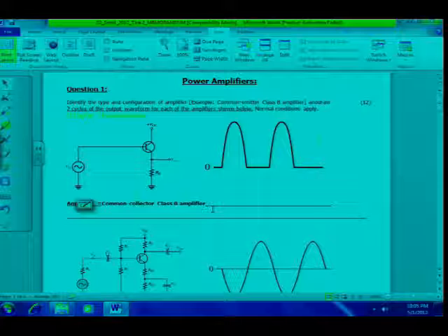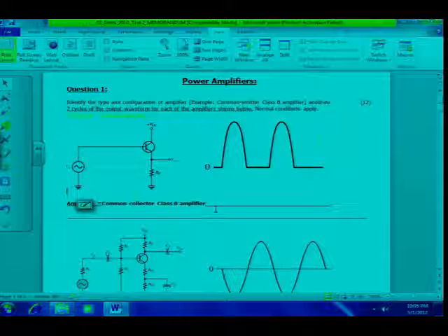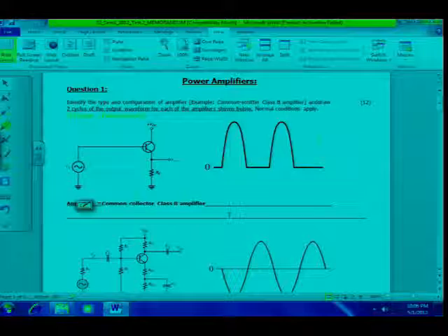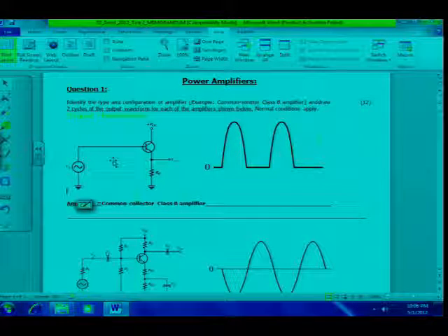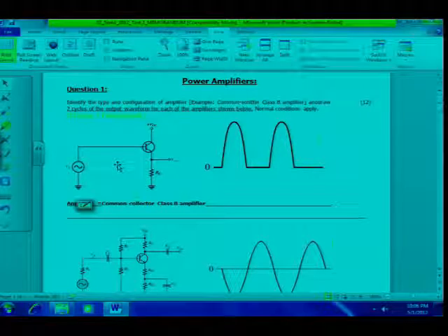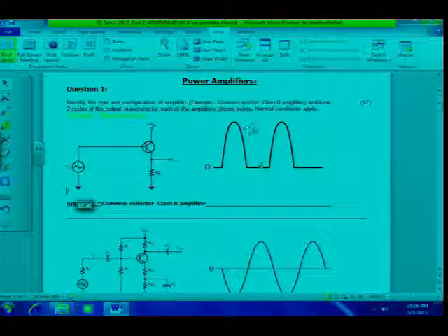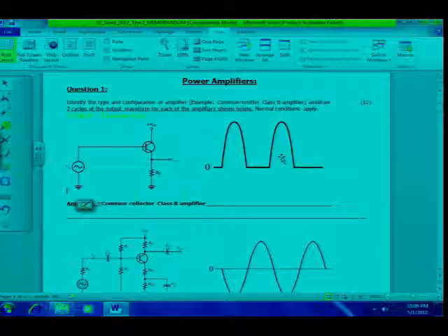The first amplifier that we can see there is a common collector. If you can still recall, how do I recognize? I go and look where's the input signal applied, where's the output signal taken from. So the remaining terminal is the common terminal for both AC and DC signals. In this case, it's the collector, so it's a common collector. You get 1 mark for that, and of course it's a class B amplifier because no biasing has been applied to this amplifier. So for the sinusoidal signal that's shown, that is what I will see on the output waveform, only the positive alternations for the 3rd mark.